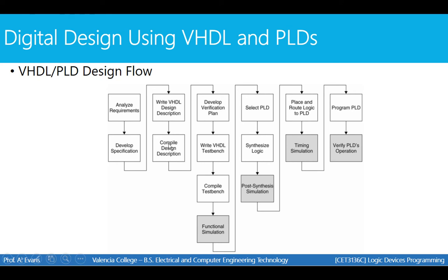Once you write your description, you'll compile that design and you'll develop a verification plan, which means how can I ensure that the code I wrote works as it's supposed to? How can I test it and ensure that it's going to work correctly once I program it on the PLD? And that's where the test bench comes in. You'll write a test bench that will verify your code to be correct. So before we ever program our code, we'll compile it and then figure out how to test it using a test bench. Once you write the test bench, you'll compile the test bench and then you'll do a functional simulation.